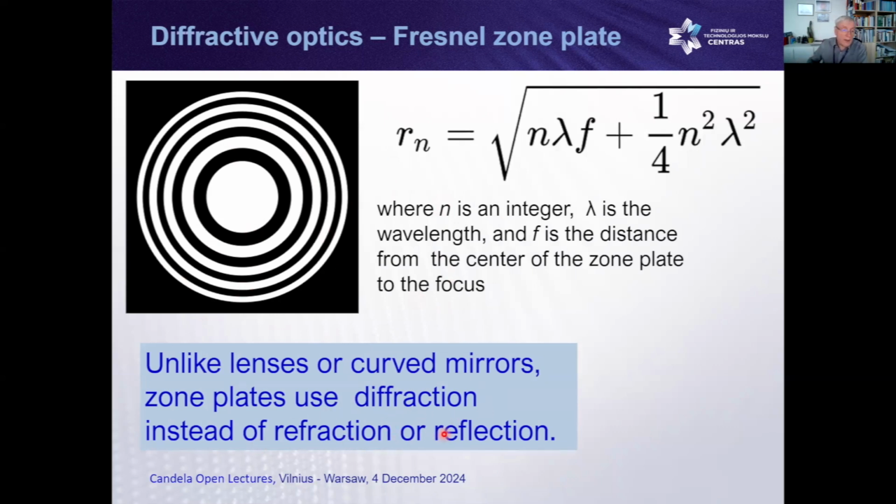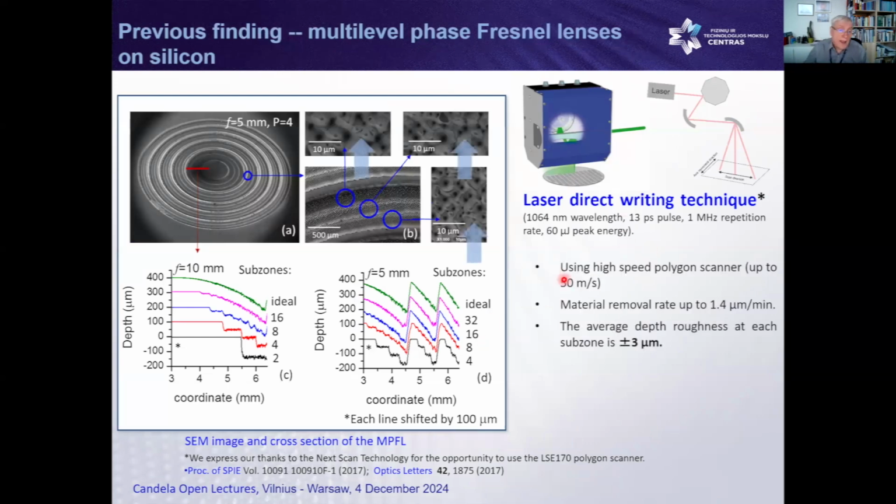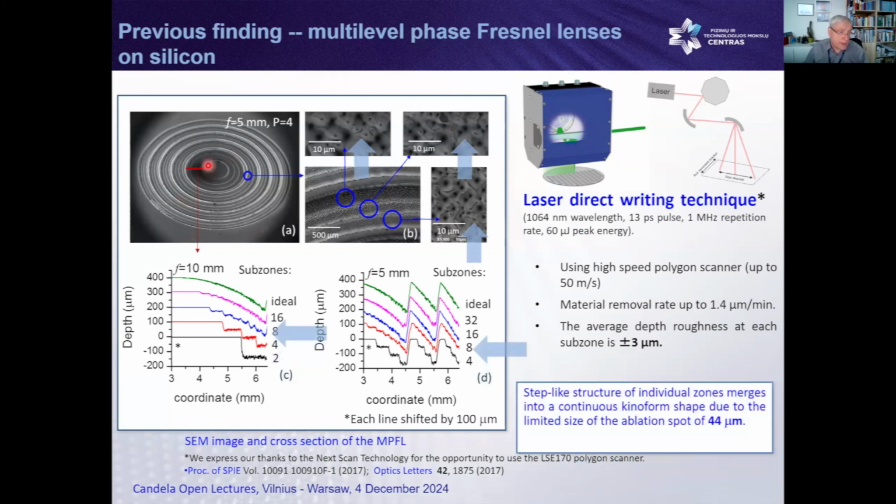So our main approach will be usage of diffractive optics based on Fresnel zone plates. And what we did, we used laser ablation technology for this development. Since we have many lasers, we try to avoid chemistry, and we use a laser from EKSPLA at the moment. And what we did is this Fresnel zone plate.